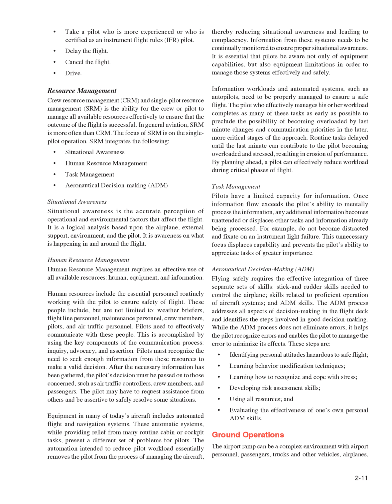These steps are: identifying personal attitudes hazardous to safe flight, learning behavior modification techniques, learning how to recognize and cope with stress, developing risk assessment skills, using all resources, and evaluating the effectiveness of one's own personal ADM skills.